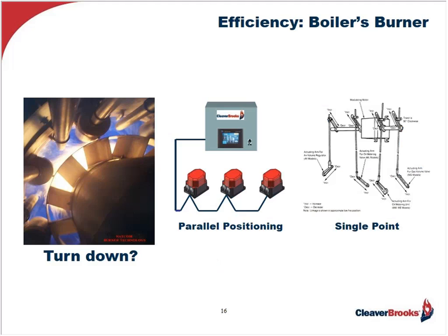And then we need to pay close attention to the turn-down capability of the burner, as I noted earlier. How's it tracking the load? Is it cycling unduly? This is very expensive if it does because of the frequent pre- and post-purge losses. We're blowing ambient air through a hot vessel, purging those BTUs to atmosphere. This, too, would be properly noted.